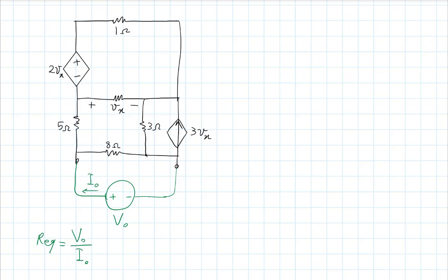Okay? Now, if I look at what I have up here, between the 2 terminals of that box, I basically have a Norton circuit, right? If I convert that to, sorry, I have a Thevenin circuit. Okay, I have a Thevenin circuit. And if I convert that to a Norton circuit, I'll end up with a resistor in parallel with that, the horizontal resistor there, right? For which I forgot to put the value. So this is, say, 6 ohm.